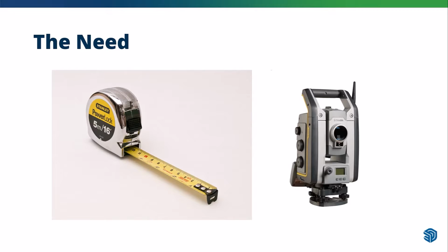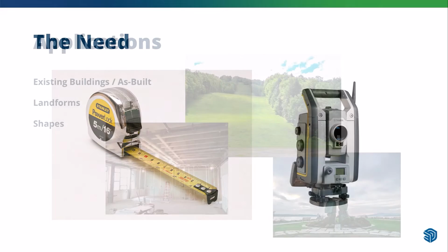All of these points come back, measured, ready to use, even if you don't need them, at least not right away. You don't have to send anybody out with a total station again to measure a few points that were missed. So whether it's a renovation project or a new construction project, there's a really good argument for getting a laser scan done and working off that, as opposed to some of these other techniques.